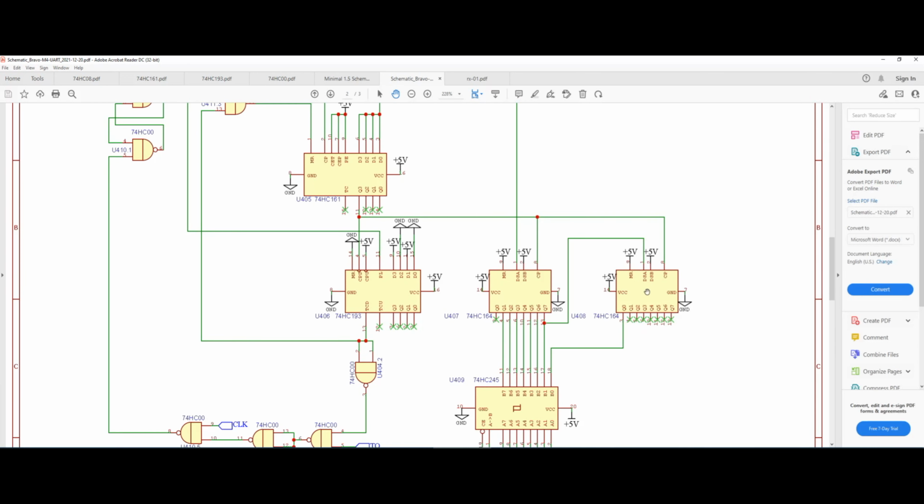Now let's go to the serial to parallel converter. Let's first talk about a couple of pins here that we have. So we have a DSA, DSB, the clock pin, and a master reset. First of all, we are not resetting those chips in any situation. So the master reset on both of those chips is tied permanently to high, and that means we are not resetting those chips. Those chips will be active all the time.